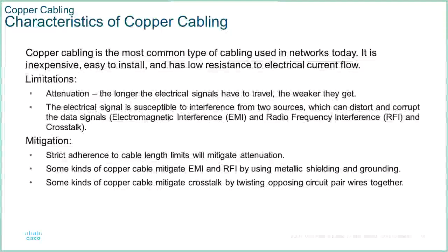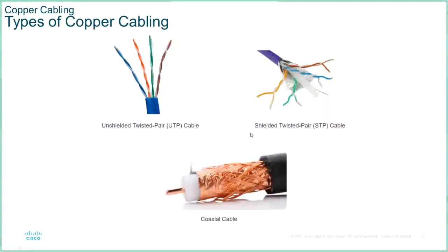Another way you can do it is to actually put shielding in, i.e. the old foil. Okay, so unshielded twisted pair is your standard Cat5 cable, and you should be able to see how the rate of twist between the blue and the blue-white pair here differs greatly from the orange and orange-white.